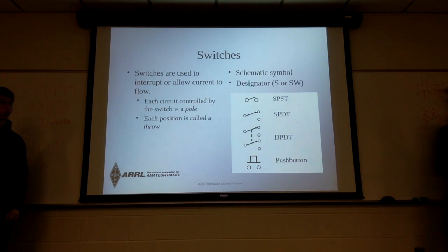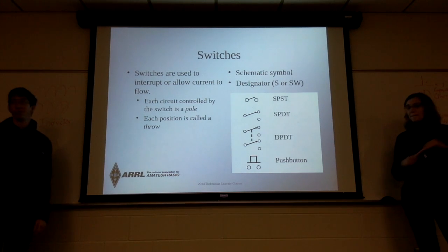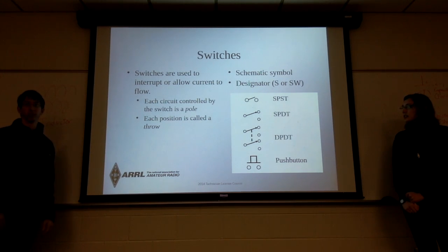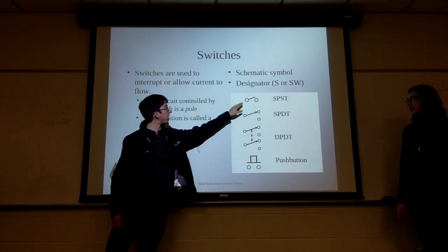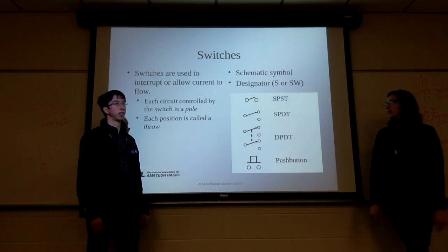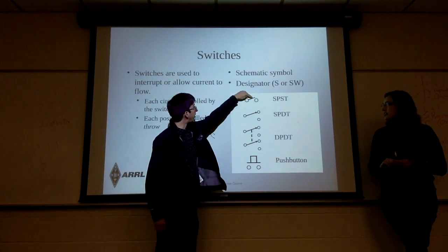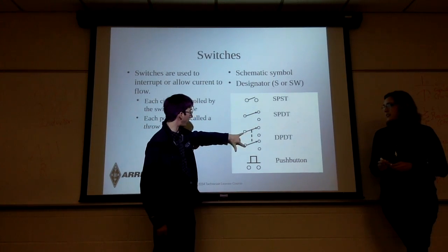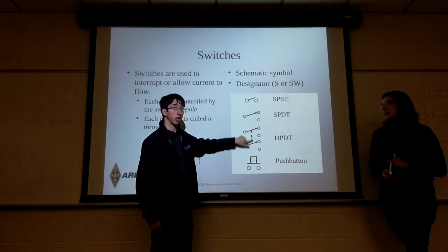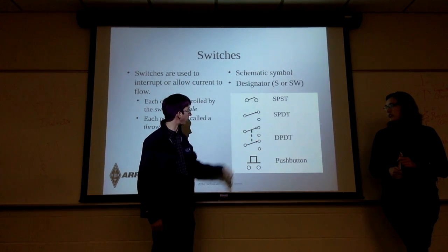Switches. So these are real switches, not like electronic switches like a transistor. The switches on the wall in the room here are momentary push buttons like this, but you'd probably be more familiar with a standard single pole, single throw. And let's talk about switch terminology. This is the pole, okay? So if we say it has a double pole, that means it has two of them, and the dashed line indicates that they are ganged together such that when you move one, it'll move the other.